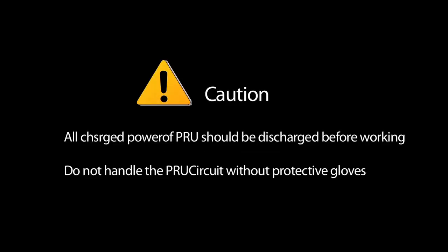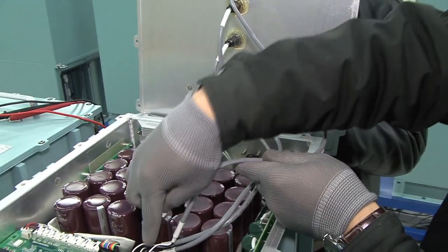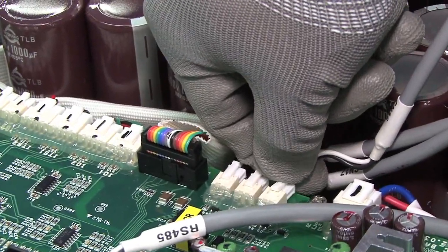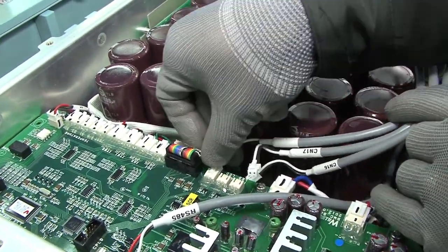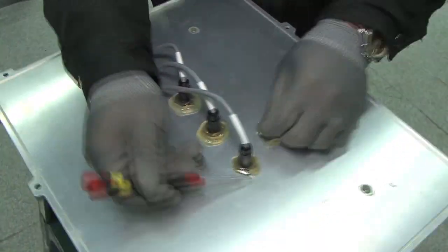Rectifier lamp. Applicable equipment and location, PRU. Step 1. Remove the top cover of rectifier by unscrewing bolts. Please do not open the top cover completely until Step 2 is finished. Step 2. Disassemble power, run, fail lamp connectors from PCB and separate body and cover. Step 3. Remove defective lamp with tools and replace it with a new lamp.